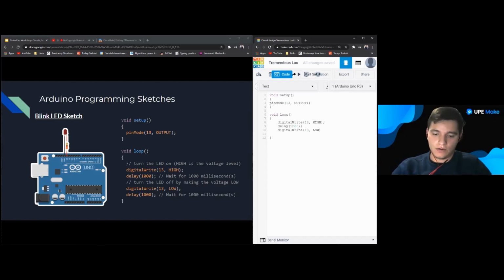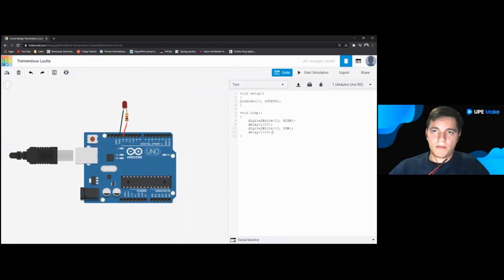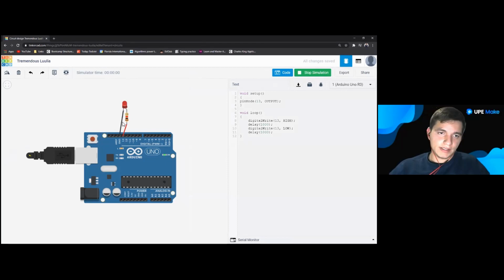These HIGH and LOW values are also custom to Arduino and the IDE, essentially telling the digitalWrite method that it's going to be on or off, and then we're going to give this same delay to it. So if we were to run this, we would see the LED here, and like I said, on the board as well, turning on and off. Pretty cool.